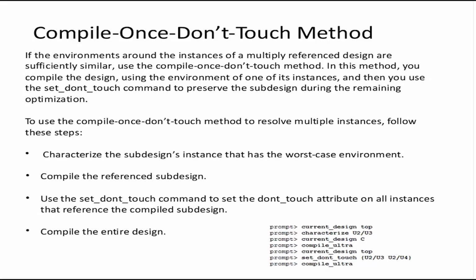We should only do this if the environment around the instances is sufficiently similar. That means all the copies, all the instances of that design, should work at similar or almost the same frequency, and even the environment conditions, the input output specifications, are similar. Otherwise, you will see a violation in one instance and not in the other. Now let's say you have an 8-bit adder again. One works at 100 MHz, another works at 200 MHz. If you use this approach,